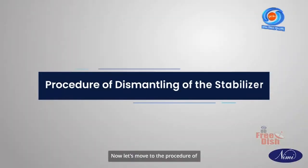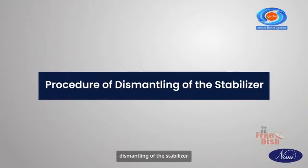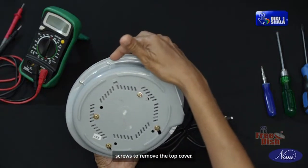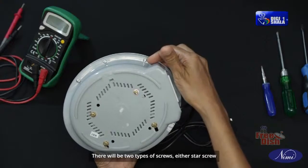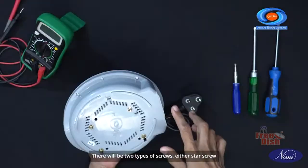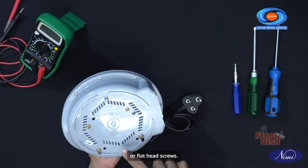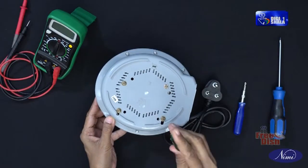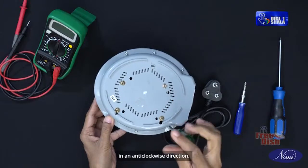Now let's move to the procedure of dismantling of the stabilizer. For that, first identify and locate the screws to remove the top cover. There will be 2 types of screws, either star screw or flathead screw. Now by using the right screwdriver, unscrew in an anti-clockwise direction.